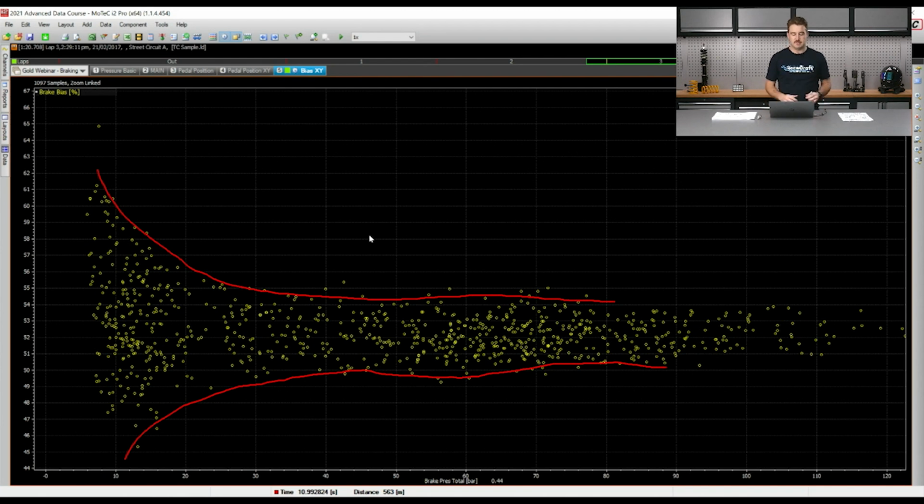So obviously it's important that we're not adjusting the brake bias when we're looking at this, but what we want to know is we can use this to understand how much compliance and how well our brake system is working. As I said before, if you're not adjusting your brake bias throughout a lap, you want your brake bias to be as consistent as possible. Inconsistent brake bias, a different proportion between the front and the rear axle, is going to give you potentially quite nasty handling traits. It'll make you start hunting down things in the car setup, whether it's suspension or tire pressures, stuff like this, when it can just be a brake bias problem that's hurting you the whole time and you didn't even realize.